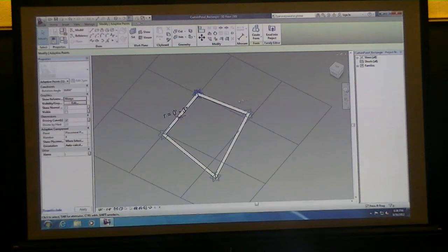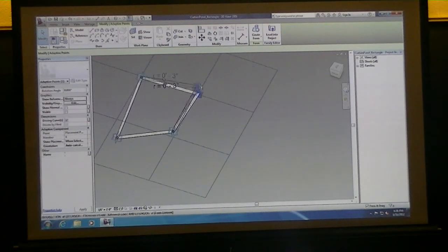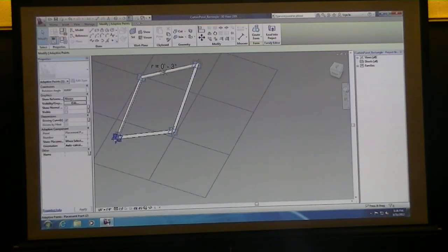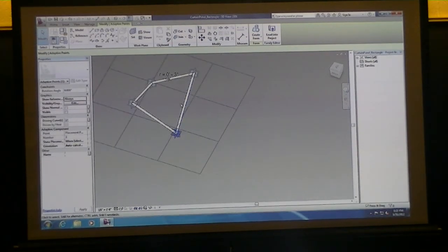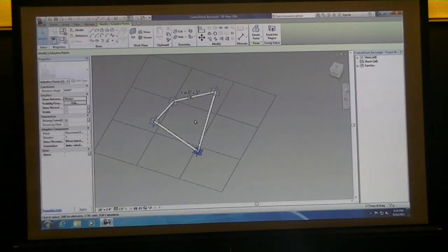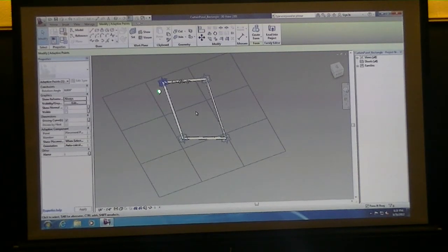So basically, when you're in this pattern, from time to time, you may want to drag your points up and down. If you drag them up and down and everything still moves with it, then you know that it's going to be adapting to wherever you're applying it. If for some reason you get an error when you move this up and down and it says cannot make the particular component, most likely that is always due to a snap issue.